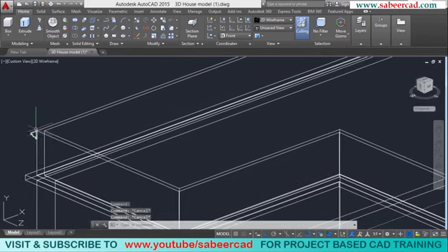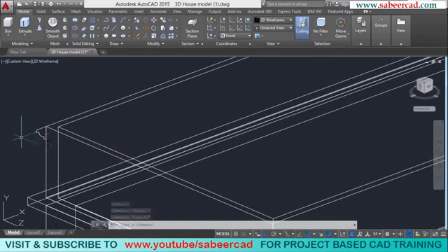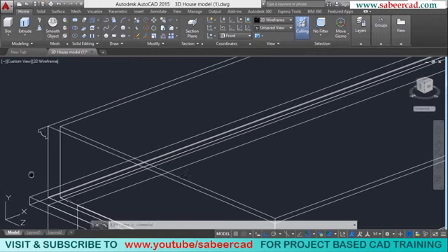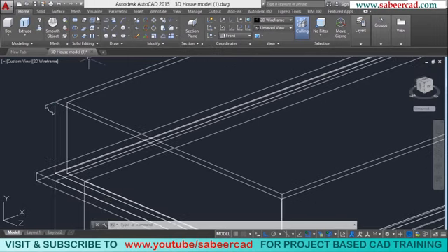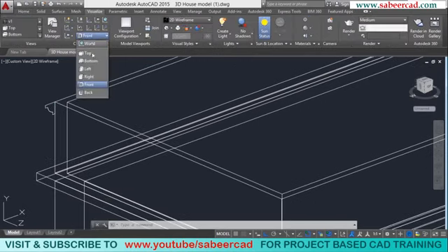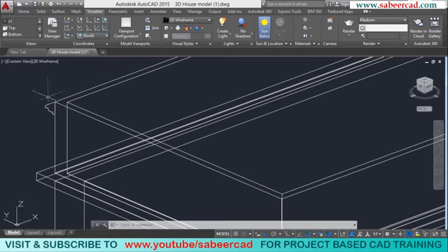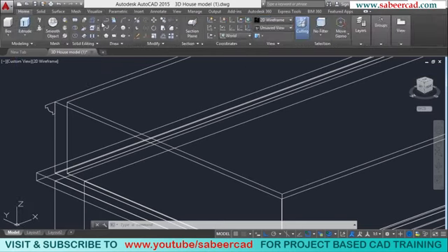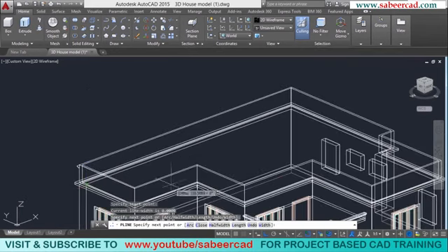Next, I'll draw a polyline path along which this profile can be extruded. But before I create the path, I should align the UCS back to the world coordinate setup. So I'll click on Visualize tab and I'll select world. Now I'll go to polyline again and I'll choose this as the start point. This is the end point.